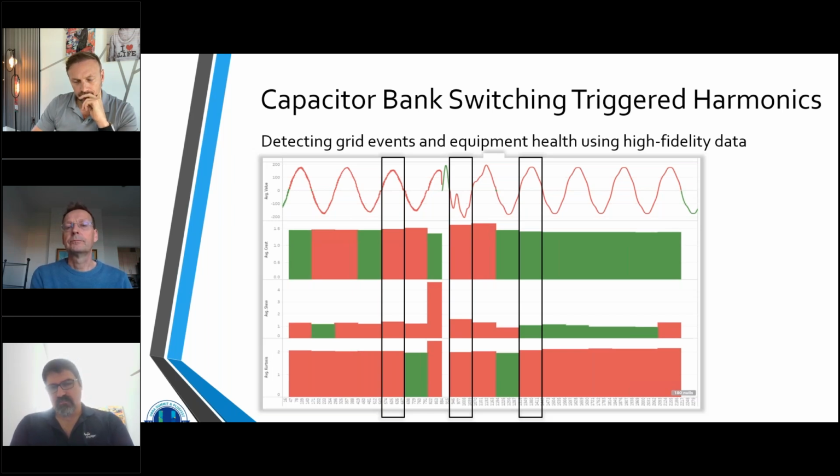who's impacted by them, and also categorize them like you would if you had a power quality recorder in the field. So we see that this is the continued evolution of how utilities will be leveraging meters as sensors for grid sensing and for distribution management. And this is just one of several applications that we're doing with this, inclusive of other things as well, like tree contacts and wildfire prevention and things of that nature.